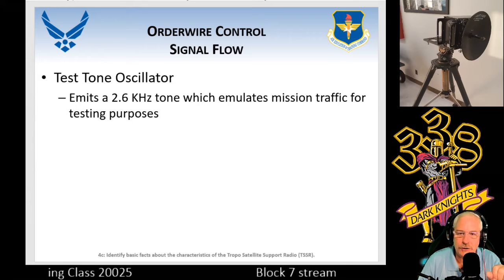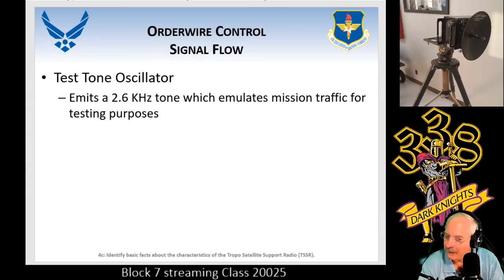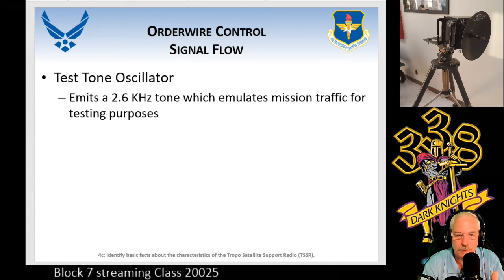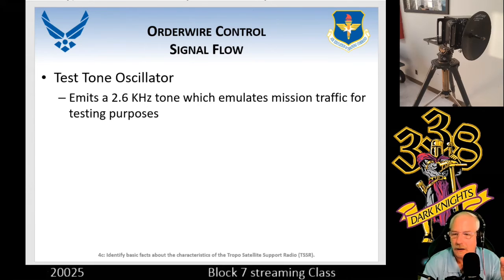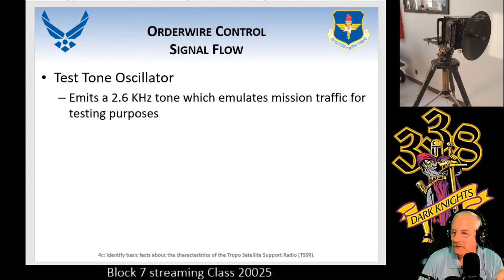Word of caution, when you're doing your labs, do not have the headset on when you do test tone. You do not want to be deaf coming back here. I've seen many a student, no matter how many times I tell them, don't put the headset on until you're doing an intercom and Orderwire check between each other. You put it on test tone, that 2.6 kHz has no volume control in your ears, and it is loud. So just a word of caution, please. Keep the headset and the handset on top of everything when you're doing test tone. You might just have to pick it up a little bit to listen in on the headset, and same with the handset. It's just a precautionary measure. It comes with a caution, not a warning, unless you keep the headset on for very long.